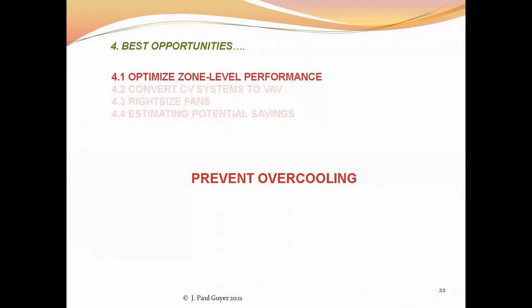If you are using a hot water coil for reheating, verify the operation of the hot water reheat valve to ensure that it opens and closes in response to control system commands.